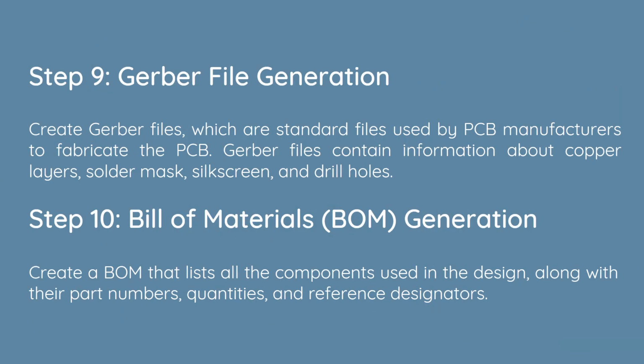Step 9. Gerber file generation. Generate Gerber files, which are standard files used by PCB manufacturers to fabricate the PCB. Gerber files contain information about copper layers, solder mask, silkscreen, and drill holes.